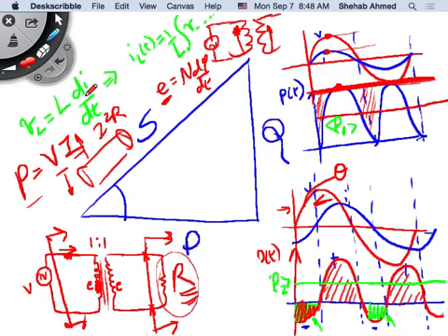Right? So there's a 90-degree phase shift due to this magnetizing branch. But then you have a big resistor here. So the sum is some inductive current and a huge amount of resistive current. So now, is the total current going to be in phase with the voltage? No, because it sees some inductance, so it will lag the voltage by some power factor angle.